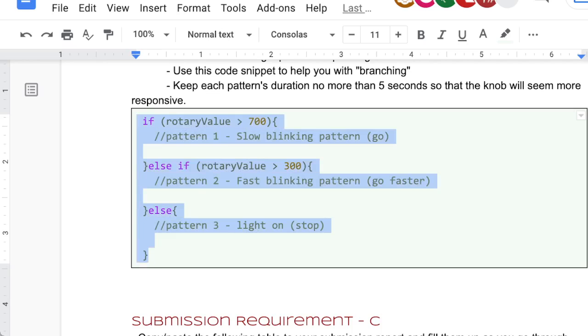Right, so you're going to copy this structure into your Arduino, and it's going to basically put it here, right? Make sure we align this. This should be 1 tap in because this is inside a loop. And what do we do here? I no longer need this code. Okay, so this is to comment it out. We go forward slash forward slash to make those not code, so the computer is not going to run those anymore. But you still need to turn on and off in here, turn on and off in here, and for here just turn it on.